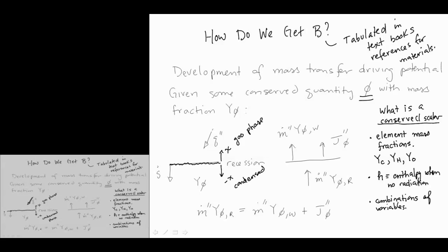Well, as we did with the flame analysis, and as we've talked about generally, in a frame of reference, if we sit in a fixed frame where the interface is held fixed, we can imagine that this can be described now as a translation of the condensed phase into this interface, and because of mass conservation issues, some transport on the gas phase side.